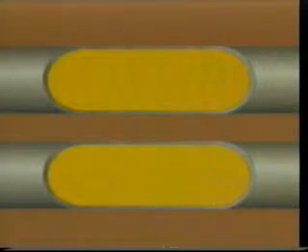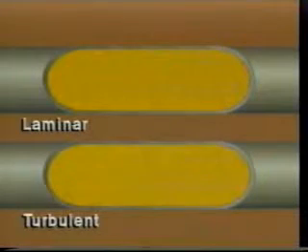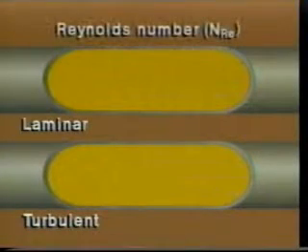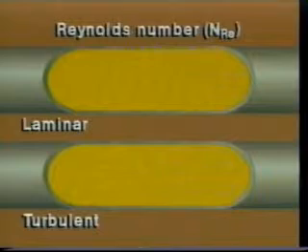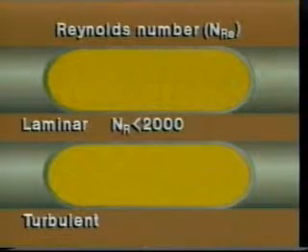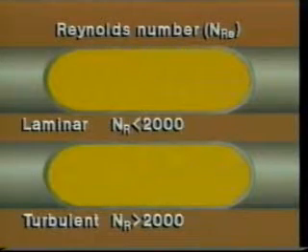In addition to the fluid composition, the type of flow occurring is very important. Fluid flow through pipe is defined as laminar or turbulent and is based on the shear between fluid layers. In most oil field applications, turbulent flow results in a greater pressure loss than laminar flow. A dimensionless flow parameter, known as the Reynolds number, is used to determine which type of flow exists in a conduit. It has been shown that laminar flow will exist through a conduit that yields a Reynolds number less than 2000. Turbulent flow will exist in a conduit with a Reynolds number greater than 2000.